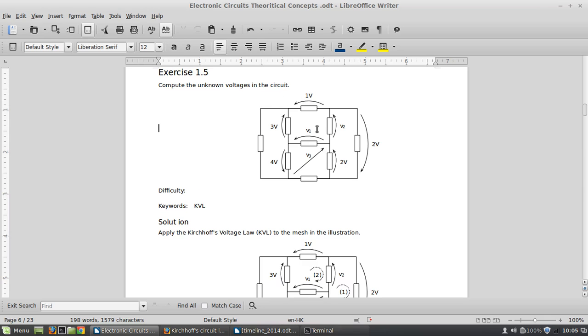As I told you, there can be numerous possible solutions, okay? Not that you have to follow the same procedure that is stated here. You can find out yourself. It's just logic, okay? You have to find it out by yourself, just using the appropriate technique. The technique is always KCL, and the rule you must follow is that current flow in must be equal to current flow out, right? And this was it for this exercise, and the solution is given here.